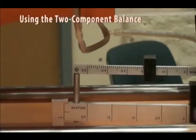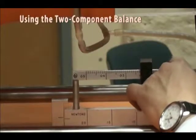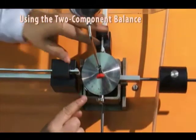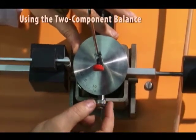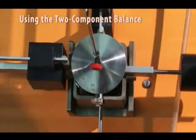Lift and drag components of force exerted on the models under testing are balanced by sliding weights along the arms of the balance until a state of null deflection is reached. The angle of attack should be set to a certain value using the protractor fixed on top of the two-component balance before setting the balance to the null deflection position.